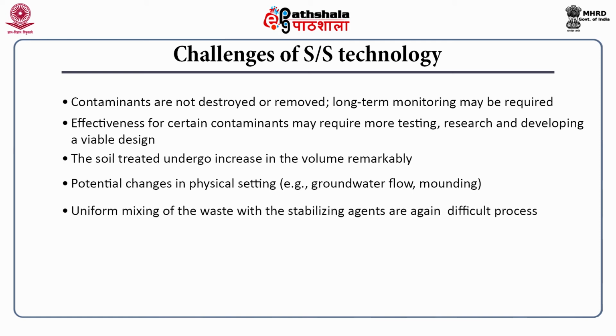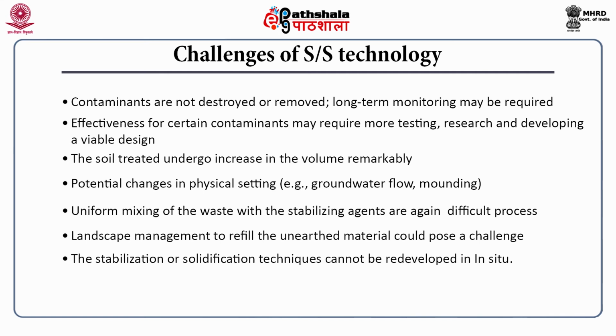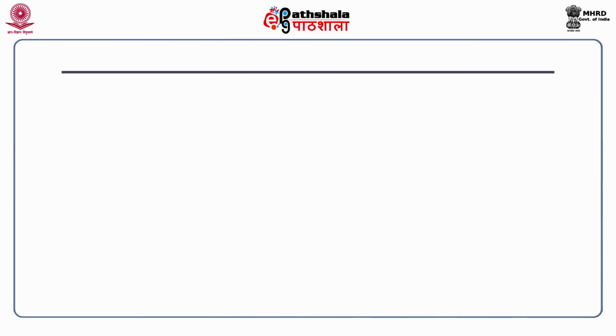Uniform mixing of waste with stabilizing agent is again a difficult process. Later modifications after applying at the site are sometimes difficult to assess and treat. Now, landscape management to refill the unearthed material could pose a challenge. The stabilization or solidification technique cannot be redeveloped in situ. Long-term efficiency cannot be ensured through this process. Now, we will study encapsulation.